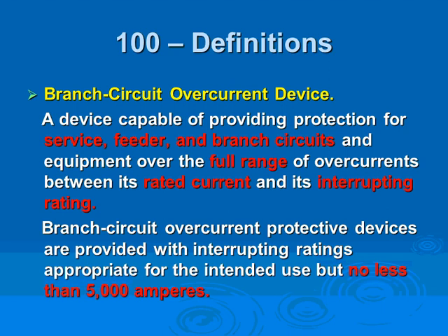So if your 20 amp circuit breaker says 20 amp, put 25 in it, it will sit there for a couple of minutes and trip. If you put 5,000 amps through it, that's short circuit. It will also trip very fast, typically within 3 cycles. So that's from the full load all the way to the interrupting load.